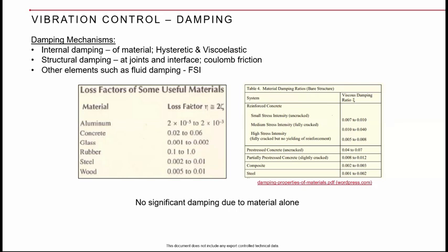So these are some from the literature. If you see, these are some indications of material damping alone that is present. Why I brought this is to make you understand that material-wise, the hysteresis damping that you see is hardly present, it is not a major contributor at all. You see here, this is varying from 0.2 percent to 1 percent, 0.1 percent, or 1 percent.